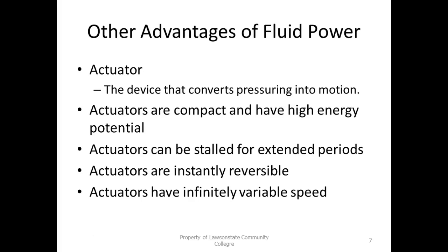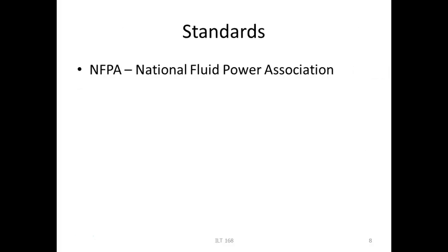But if you ever looked at the hydraulic cylinders that moved the big old control surfaces, they were probably less than 2 inches of area. But they ran 3,000 psi. With 3,000 pounds per square inch, if you were pushing that against 1 inch of area, you could generate 3,000 pounds of force. So that's what's really nice. You can have these real small actuators generating a lot of force. Could you do that with a motor?